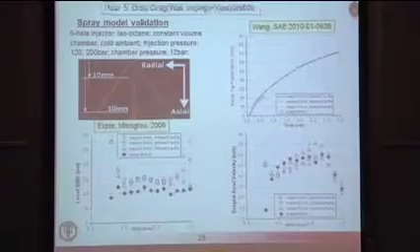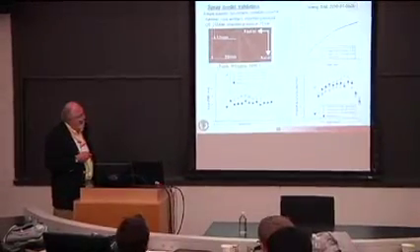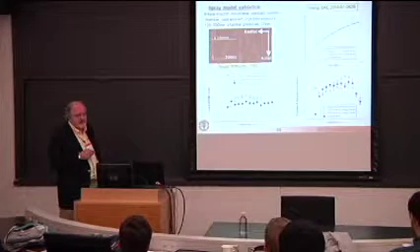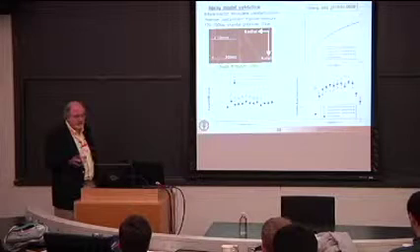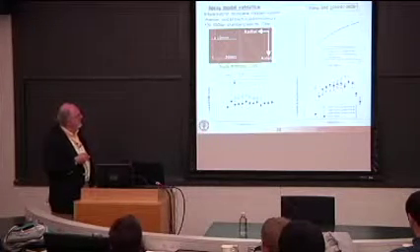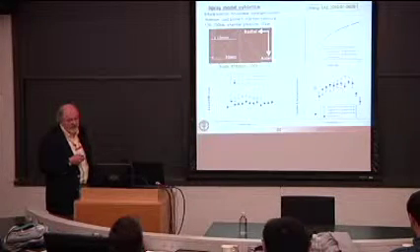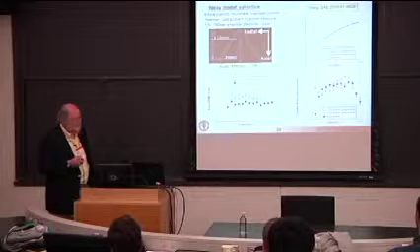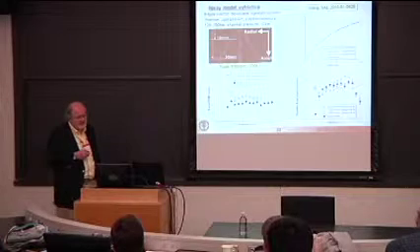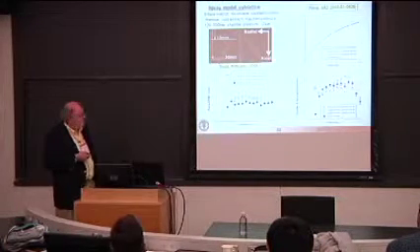Okay, so to validate these models, there's a lot of data out there, but in a way it's kind of disappointing because the interior structure of the spray is not really accessible except through, say, X-ray techniques and so on. So we rely on things like the spray tip penetration as a function of time, measurements that are relatively easy to make, photography, let's say. And then with PDPA, or droplet size instrumentation, we get an idea of the droplet sizes in the spray.